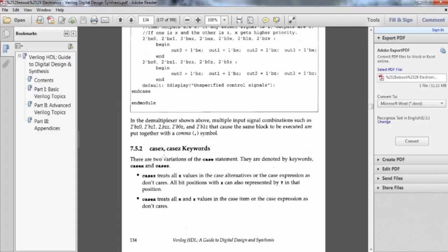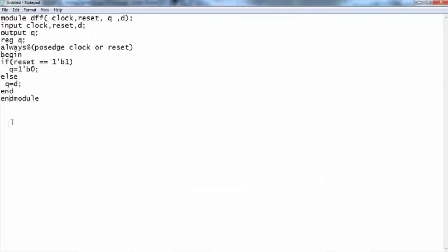Basically I am telling you about the case statement, which we are using multiple times. Using that case statement, you can write down the program of an ALU, arithmetic logical unit of a microprocessor or microcontroller. As I told you earlier, we'll be designing some blocks of the processor as we also learned about the programming. So now you can make two modules of a processor. One you can make is an ALU with some instructions, for example, let's say 10 instructions.